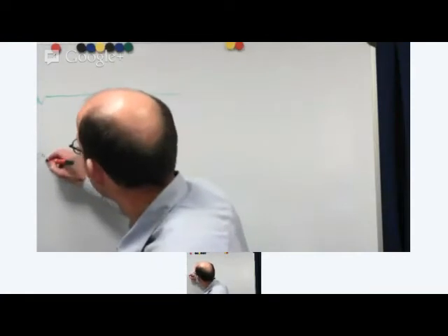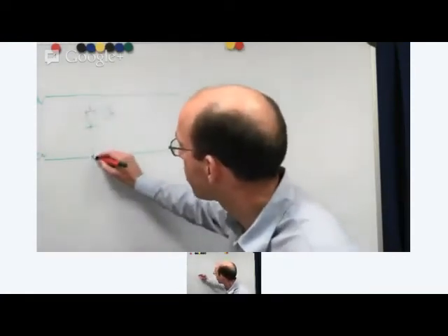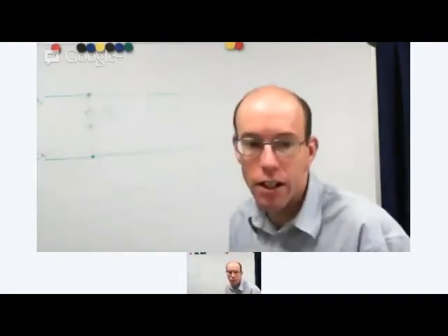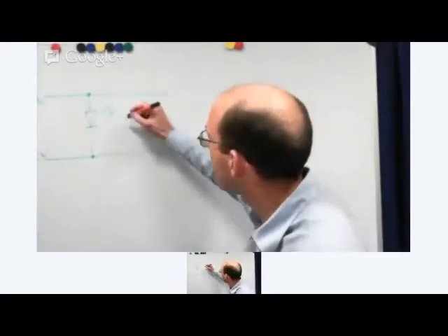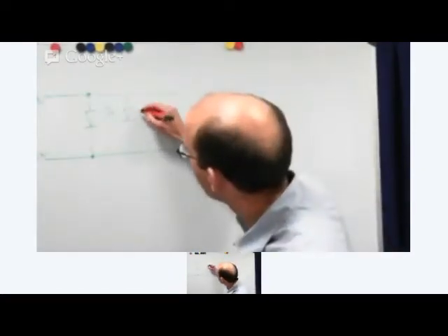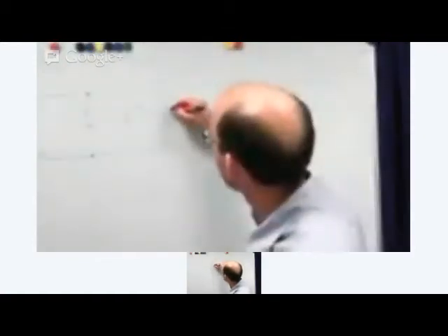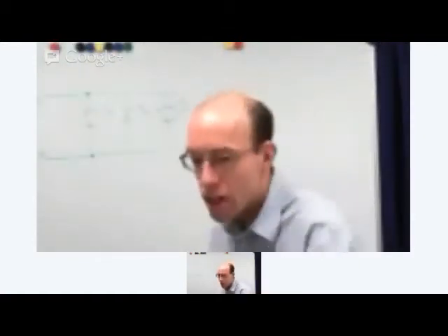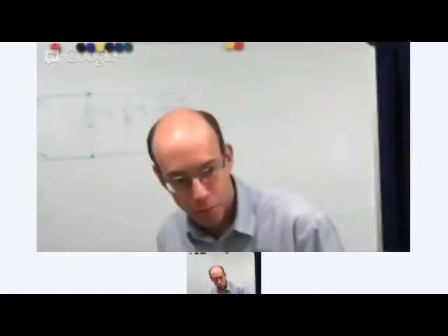If we've got 5 volts there, then it's simply a case of just connecting the LED onto the parallel. If we want to put an extra LED on, we just connect that one in parallel like that, and we can keep adding as many of those into the circuit as we like. So colour changing LEDs, really quite straightforward, no worries on those.